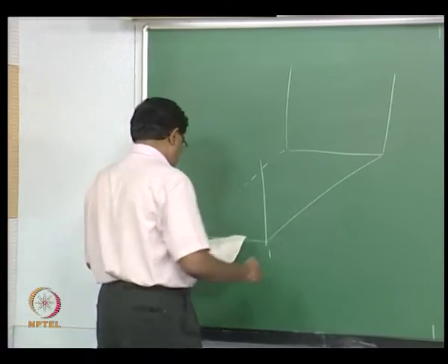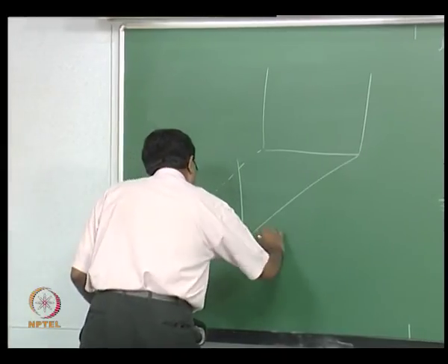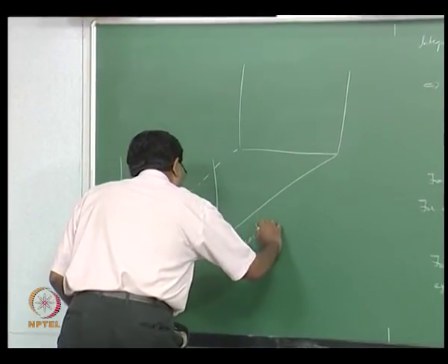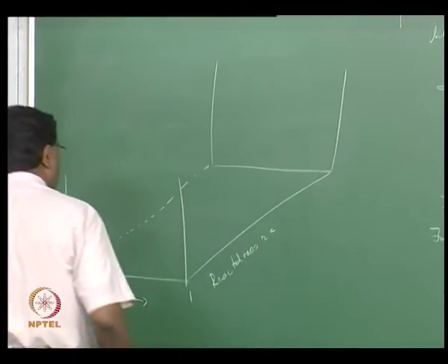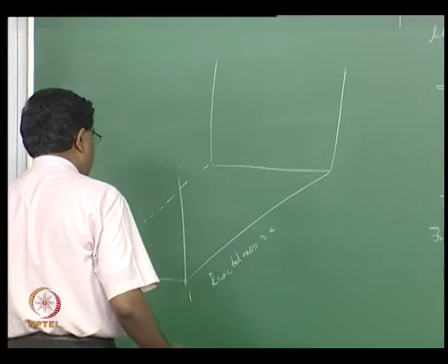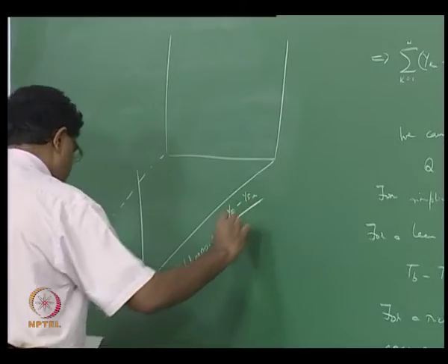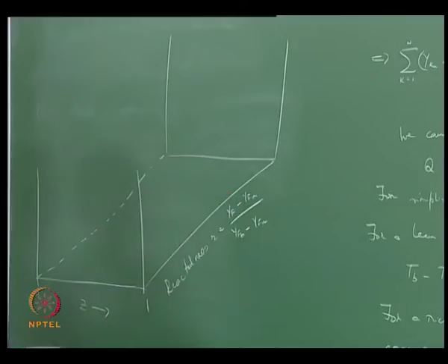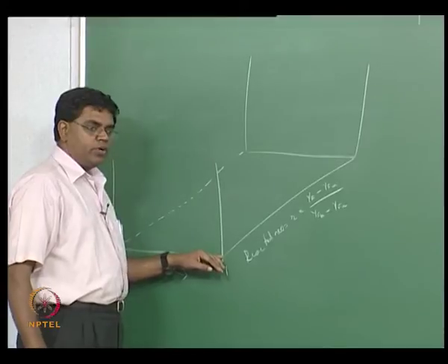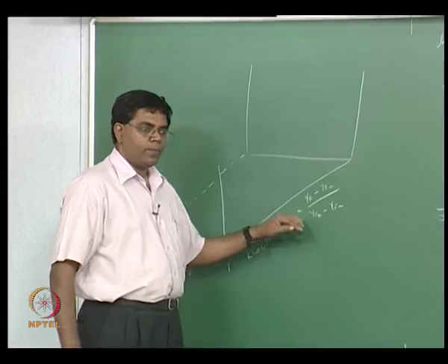And along this third axis we now have a variable called reactiveness. What's the level of reaction that's going on? How do you monitor this? By looking at YF minus YFU divided by YFB minus YFU. So when you started out, YF is equal to YFU, so R is equal to 0.